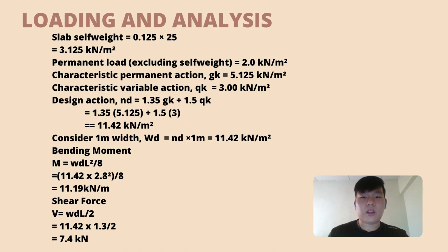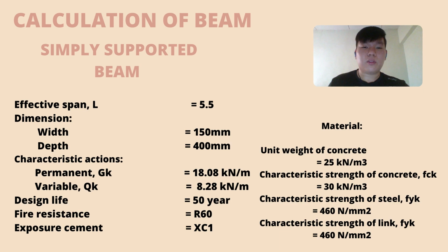While for the loading and analysis calculation, the step self-weight is 3.125 kN per meter square, and the design action is 11.42 kN per meter square, and the bending moment is 11.19 kN per meter, while the shear force is 7.4 kN.